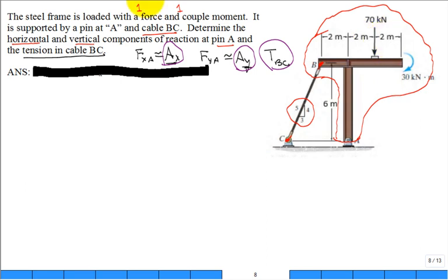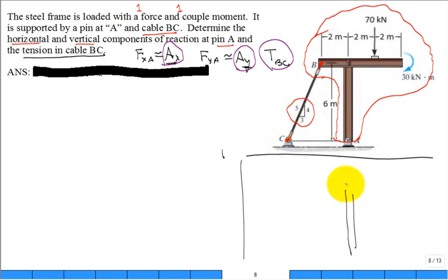So when you do this, maybe if somebody said, put your free body diagram in this box for this problem, you would be forced to re-sketch as best as you can do it. You would have a tension force, tension B to C, and maybe you even move that little similar triangle up so it's a 3, 4, 5 orientation. You then come down here and you would have maybe A in the X and A in the Y. They're applied at point A.